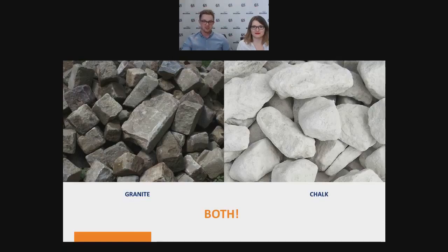So while that's true, granite is a harder material, we must remember all of the other factors. So we don't know anything really about this situation. We don't know the size, we don't know the quantity, the velocity, or any of the other useful information about the process. Over time, chalk, as you've all stated, could quite easily cause as much damage. There might be one piece of granite going through this system every day, or there might be 25 tons worth of chalk going through the same system.